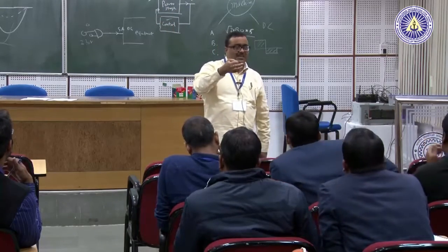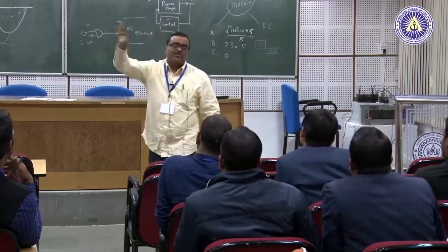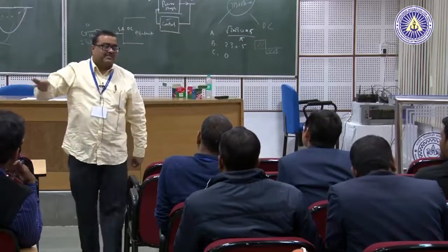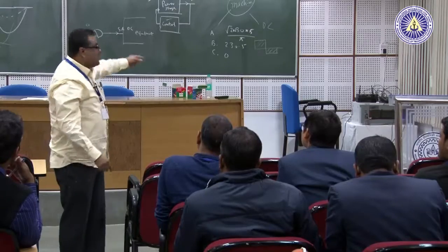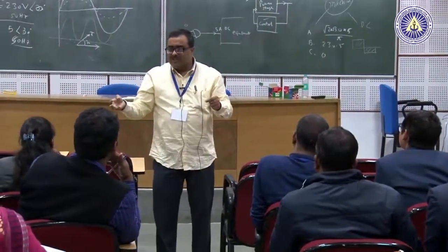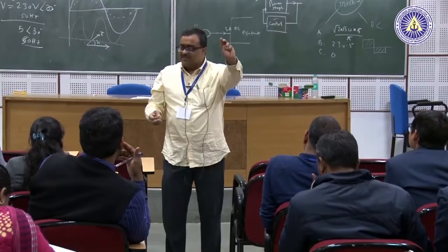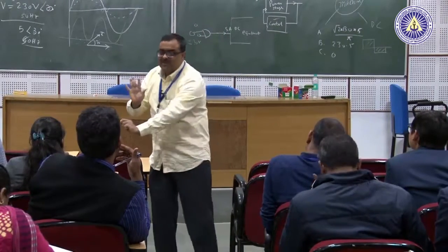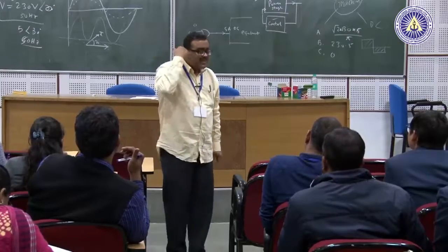In a sine wave inverter, the harmonics are put at the highest frequency, but in a square wave inverter, by nature, if you look at the Fourier series of a 50 hertz square wave, you will see there is a 50 hertz, a 150 hertz, 250 hertz, all these components. That is why they will make sound.